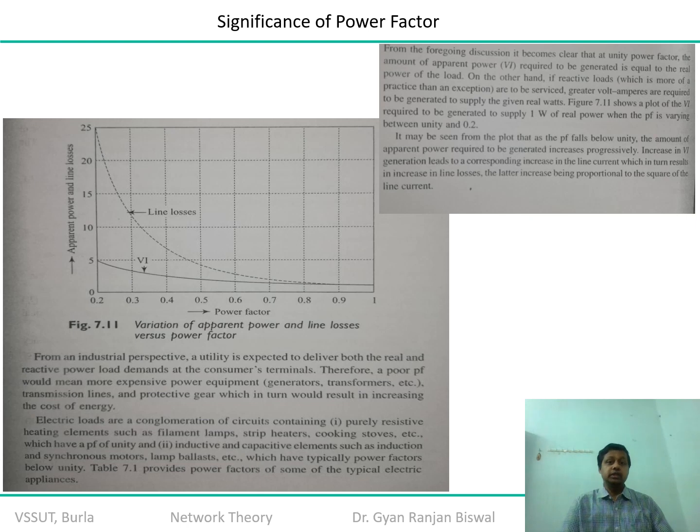Remember, this transfer loss is also added into the account of your bill. So the more the line loss, to consume the same amount of power, the higher the bill you will get. So remember that the quality of the conductive surface is also good for your reduced bill, and at the same time, the higher the power factor you can attain is also good for your energy bill, because then you will get a lesser energy bill.